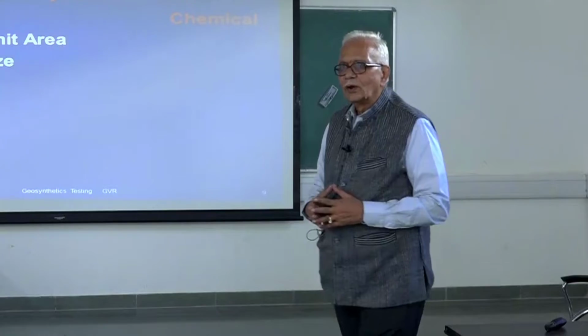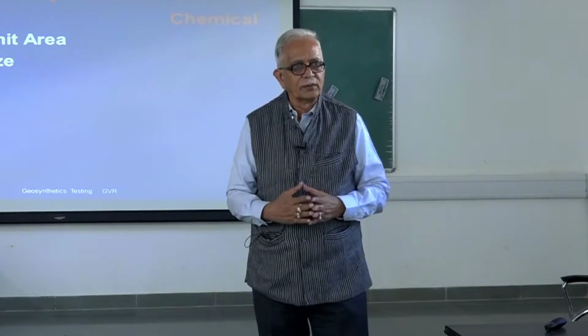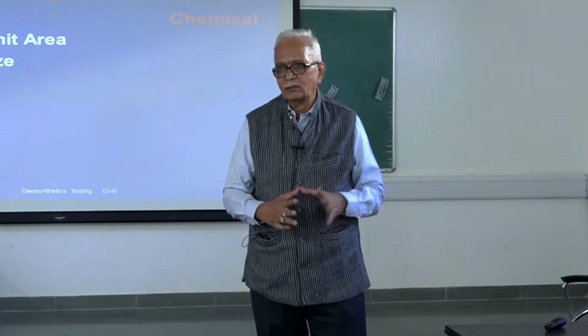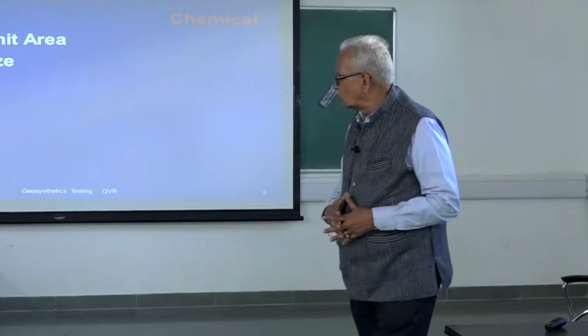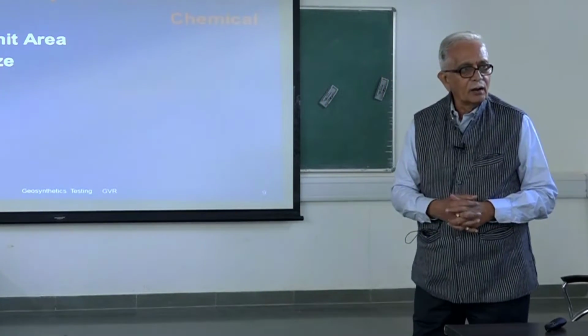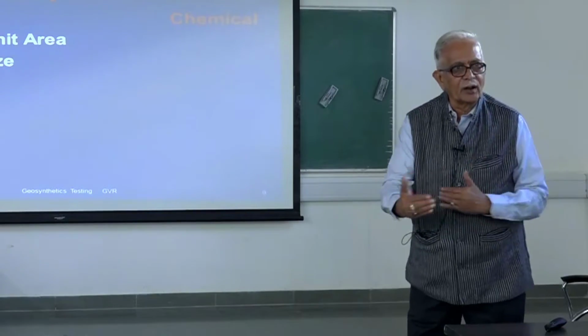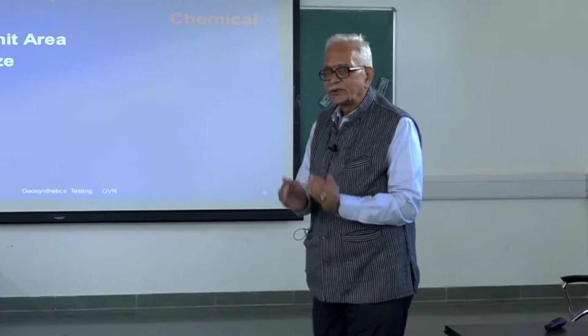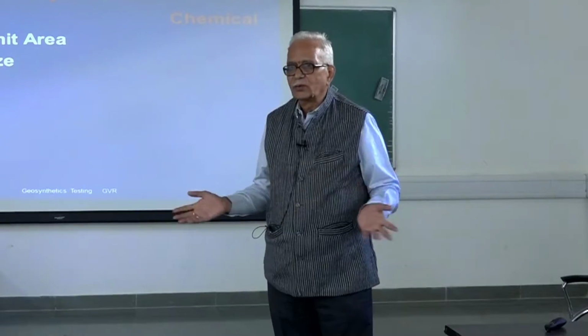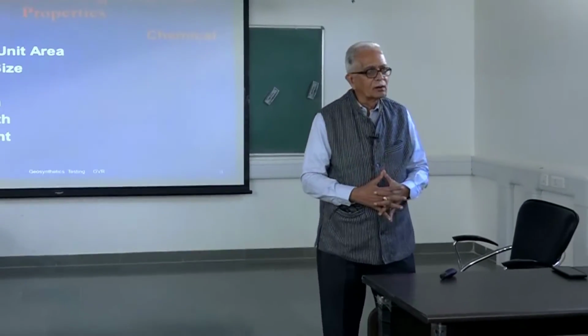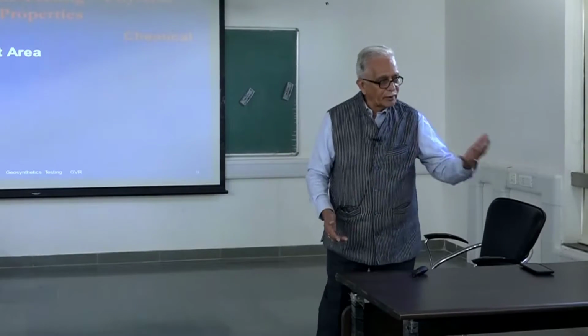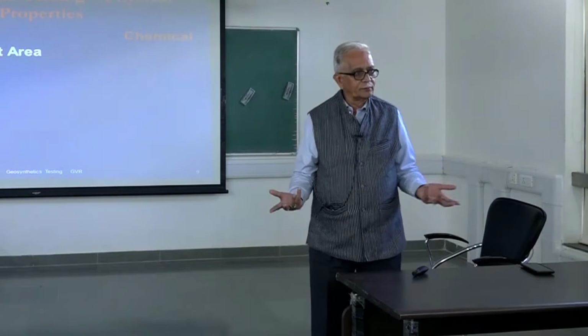So here also we are going to do a number of tests to assess the behavior, to assess the quality of the entire material. Thickness is going to give us that, and coupled with the mass per unit area, naturally these are parallel to each other one way. It should be the same throughout the length and breadth of the roll actually. So here also is a parameter which is a simple one to measure. You define the size and shape, just weigh it.